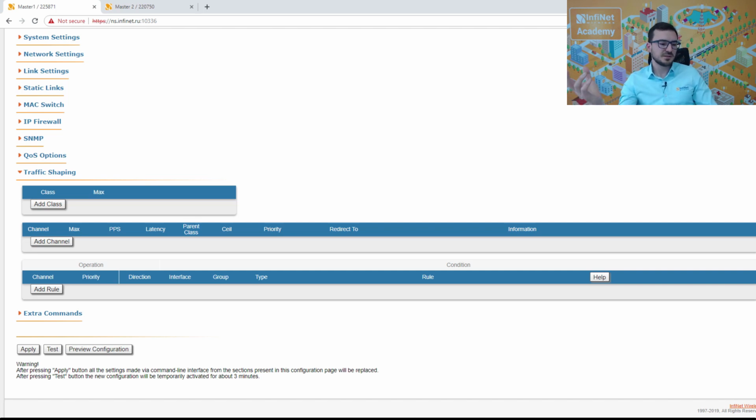Right, so Sami, if you need an XG1000 link with at least 700 megabits per second of capacity at 11 kilometers, and you also have high interference, yes, my colleagues at support will be able to help you with this request, because you have to perform a thorough spectrum analysis there in order to see whether you will be able to achieve that capacity or not. It depends on the amount of interference. And you will also have to use some high gain antennas with really narrow beams, and that's how you might be able to trick the interference a bit. And maybe you will be able to achieve the capacity that you need.